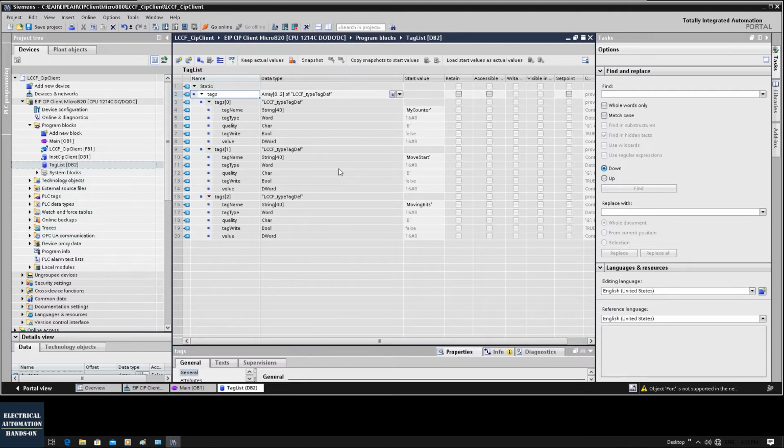In this case, the target PLC is the Allen Bradley Micro800 PLC. In this area, we need to type in the variable name. Also, we need to assign the tag type. So we need to review the manual. We can temporarily leave this area.